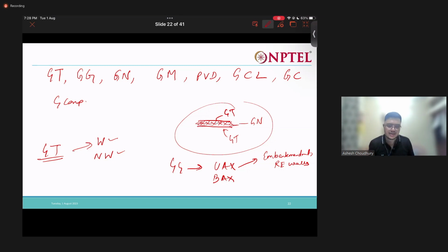In those cases, uniaxial geogrids are generally used, and biaxial geogrids are generally used below roads to reinforce the road. Say you have a small portion of a pavement, and you want to reinforce the base, the subgrade of that pavement. In that case, we use the biaxial geogrid, and also maybe below railway tracks. In all those cases, we will use the biaxial.